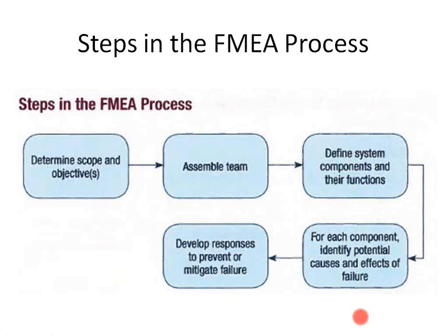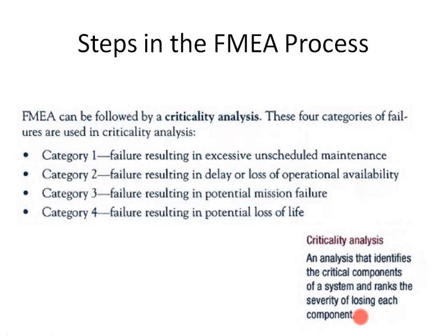Talk about assembling a team, and usually this is a multidisciplinary team that may be looking at the different issues. Define the system components and their functions. For each component, identify potential causes and effects of failure, and then develop responses. So it's a really systemic process that you go through, and it takes a lot of time, unfortunately. It is very time intensive. But it's really for high-cost things, okay, like the Bay Bridge, something that's really expensive. You want to look at where the failure points might be, and then make sure that these things don't fail as part of that.